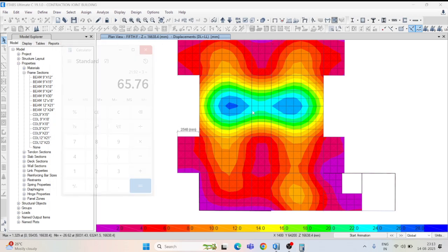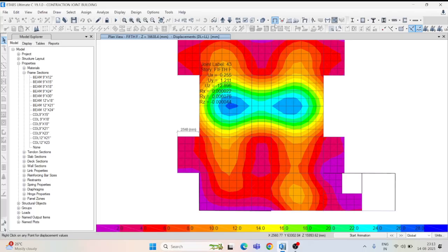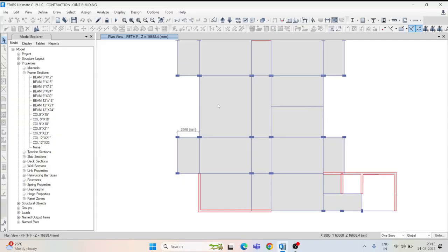So what happens is that again you will have to do one thing: here we have to add one more beam. Okay, and then after that you have to divide this slab and create one more beam here, and then again the same process. So automatically it will be getting safe. My motive was to show how we check the deflection in creep coefficient. I thought you understood what the process is for that.